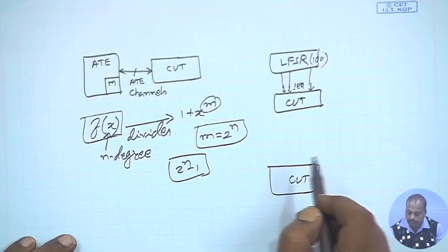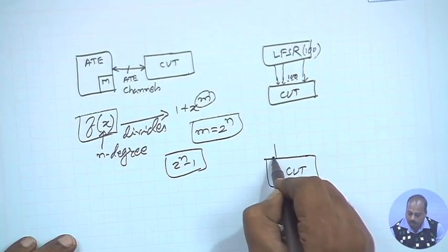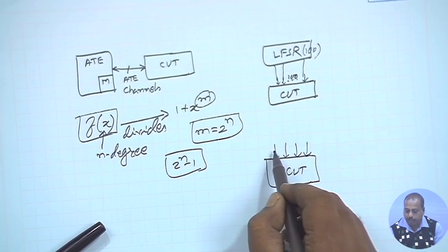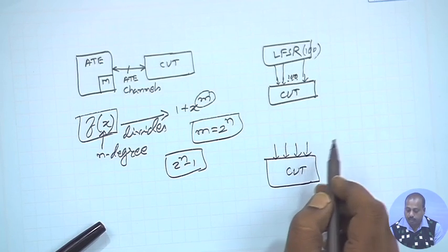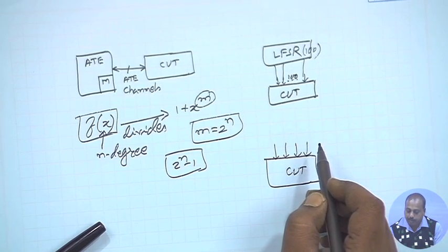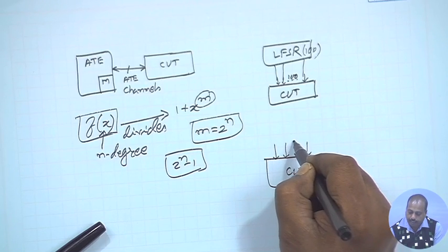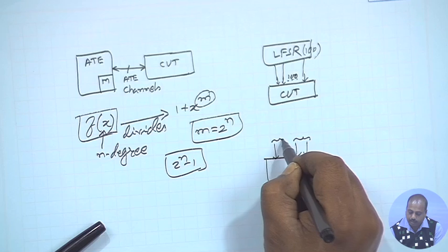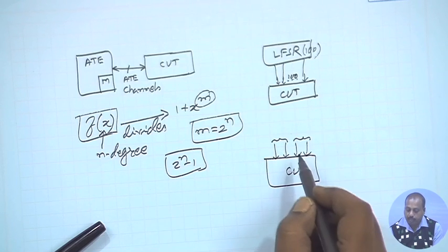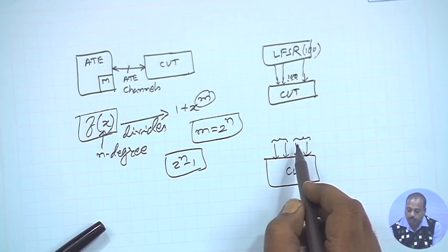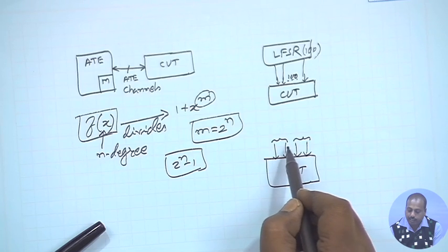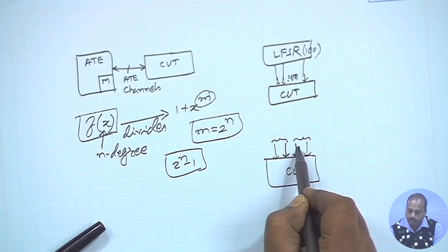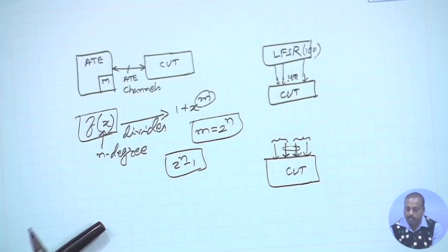that we are trying to test, in exhaustive testing, if it has these inputs, it will generate exhaustive patterns for all the 4 inputs. But it may be sufficient that I generate exhaustive patterns for these 2 and for these 2, and not for the remaining ones. So the patterns that I apply are not exhaustive when we consider, say, this pair.